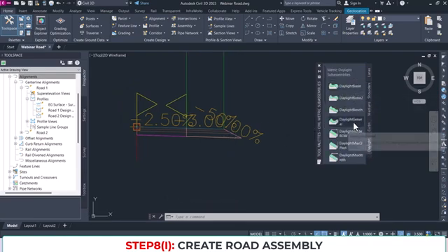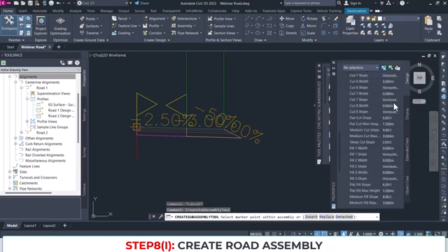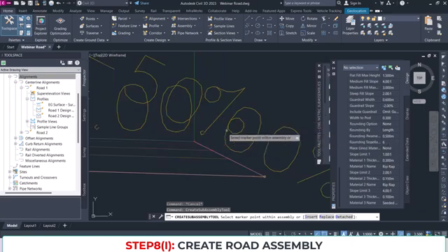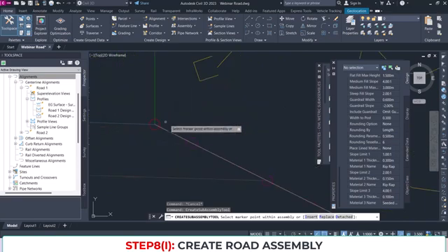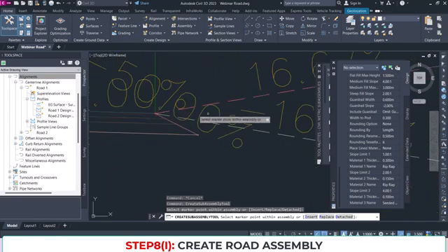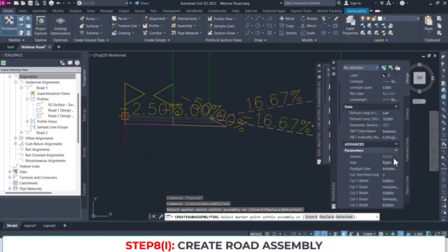So we use daylight general. You can adjust all these parameters, but I don't want to go into all these things, or else I will bore you. But you need to have the slope limit be 2:1. I'll just put it there for now. This class is already longer than I wanted it to be. So just click on this. Okay, you have your daylight. Of course, it's to the right, right here, as you can see.